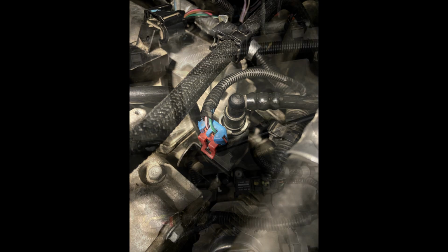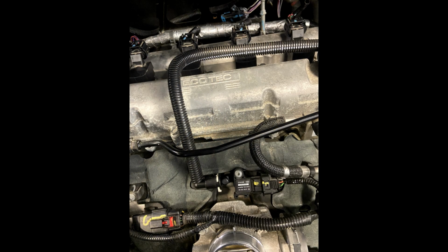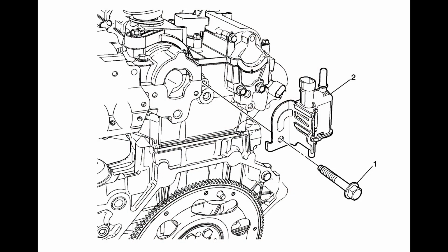There are several tests that the vehicle will conduct in order to monitor the operation of the EVAP system. First is a purge solenoid valve leak test. In this test, the ECM commands the purge valve off and the vent solenoid on, and this seals the system as the vehicle watches the fuel tank pressure sensor for an increase in vacuum.